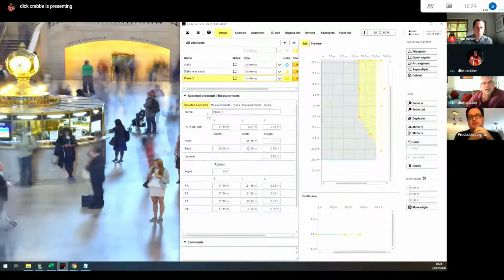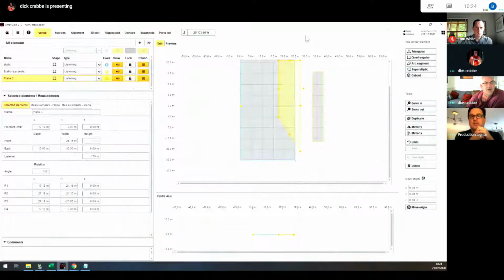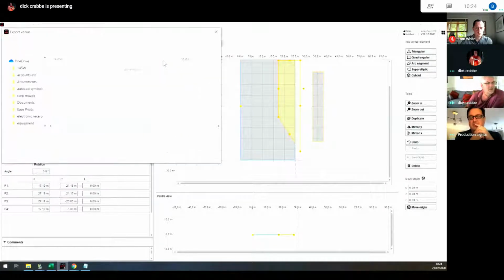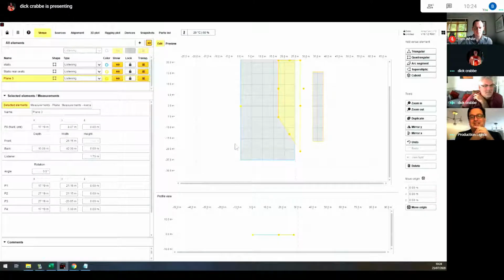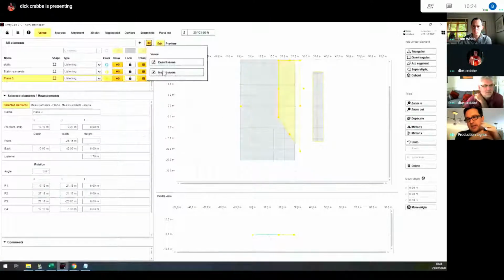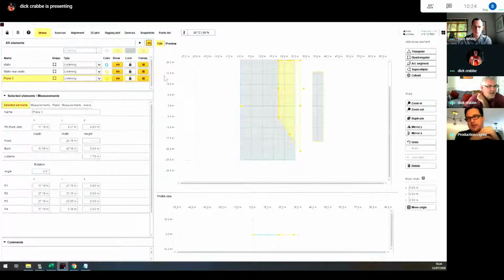So you can manually do that, and with the basketball arena I found it was much easier to... I've just overwritten it. Don't do things live. But you can bring it back in, so you can go in and edit in the text editor, a bit like the Excel sheet, and then drag it back into ArrayCalc.